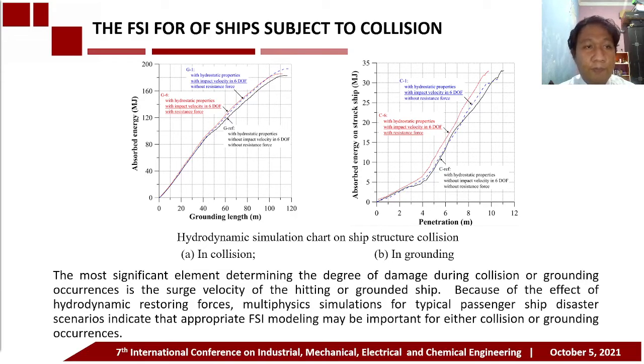In the graph, hydrodynamic simulation is shown on ship structure collision. A is collision, B is grounding. Because of the effect of hydrodynamic restoring force, multiphysics simulation for a typical passenger ship disaster scenario indicates that an appropriate FSI model may be important for either collision or grounding occurrence.